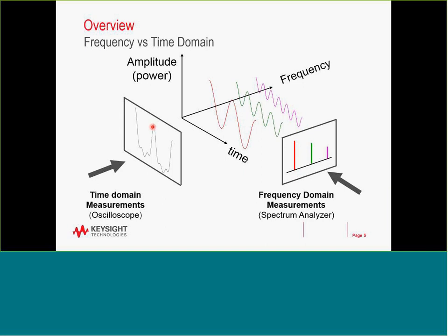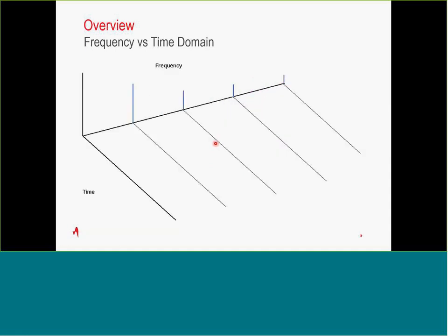They might be quite small. On the spectrum analyzer, though, where the dynamic range is quite a bit higher, you could discriminate and see that there are some frequency components that you wouldn't be able to see with the oscilloscope. It's two domains: time, which is the oscilloscope, and frequency, which is the spectrum analyzer. I have a little animation here showing the signal propagate over time.